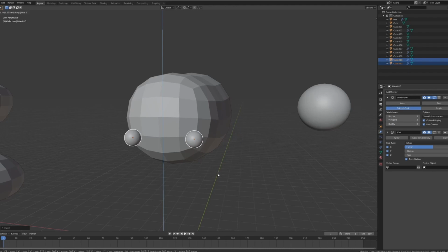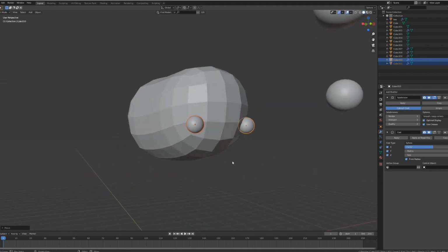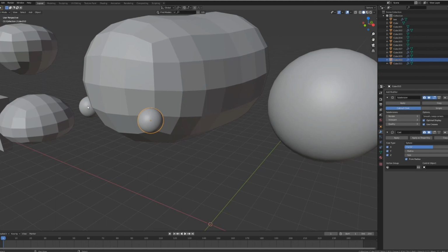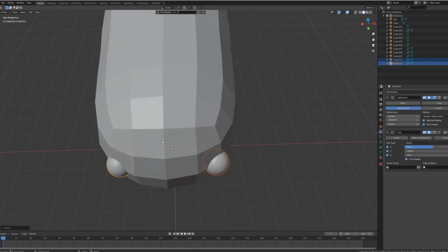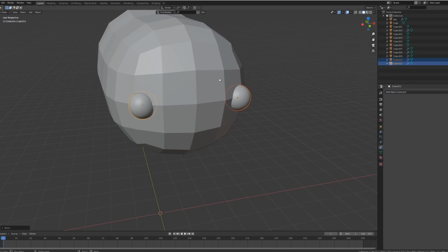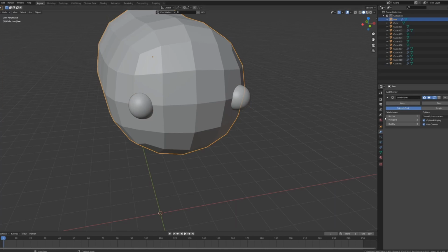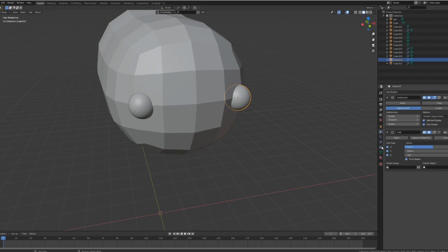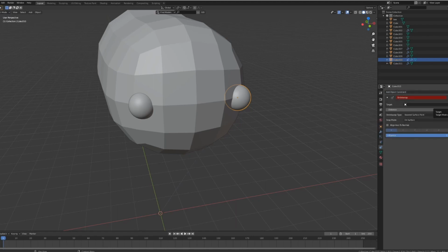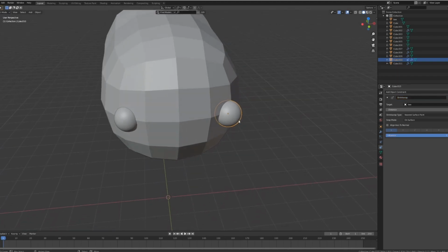And once you decide on the position, or let's say you like the position that you're in, you can then try and remodel some stuff. Now that we have our position, for example, we're going to just leave them in the middle position like so. So this is going to be our middle position. Now we can start and look at the actual structure of the eyes. One very useful trick that's going to help you a lot is, first of all, we need to apply the subdivision of our character. So I'm going to go into the body and apply the subdivision. Then I'm going to choose one of the eyes. Then I'm just going to go under Object Constraints, and I'll be choosing the Shrink Wrap one. Target, I can click on the eyedropper and then just click on the object. And this is going to actually position the eye directly on my body.